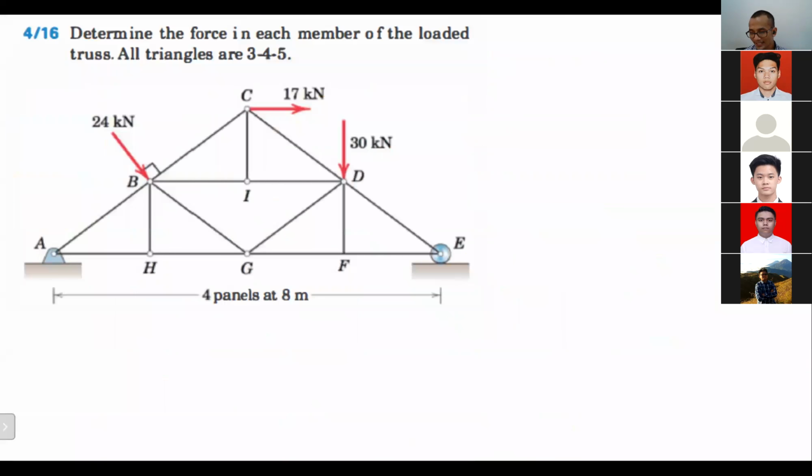Okay, now in order to make it simple, we can try to reanalyze our homework with the same analysis. Can we find the first type of zero force member here? No, the first type. We have two types, right? The first type and the second type. The first type first: where only two non-collinear members are joining at one free joint.